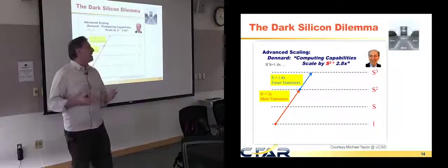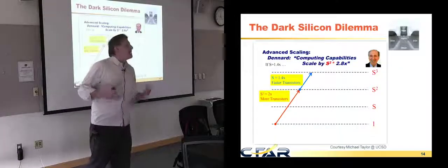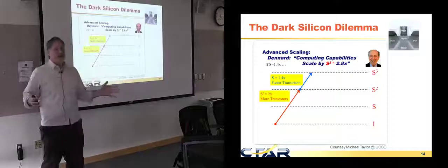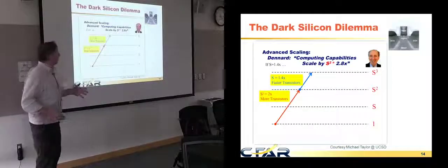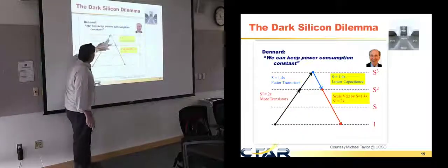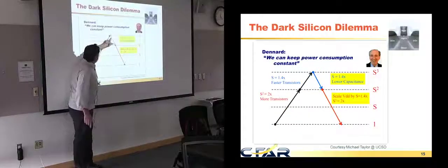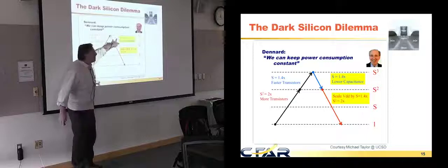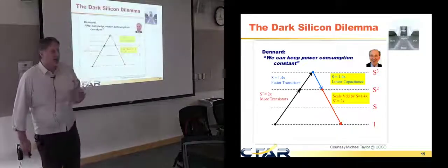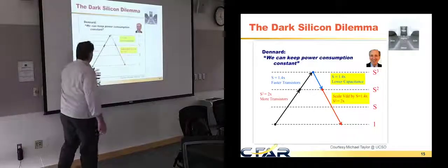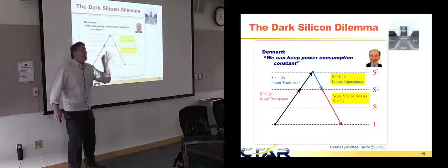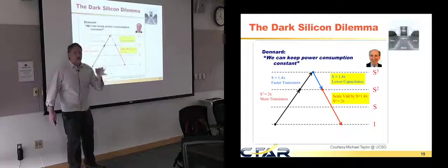And the technologies for bringing more power on chip have advanced at the slowest rate you could possibly imagine. But fortunately, because of Dennard scaling, Dennard noted that if they're running faster because they're smaller, they're also using a similar lesser amount of power because they're smaller, because there's less charge in their channels. And then here was the kicker. We could make up the rest by dropping voltage by a factor of 1.44.